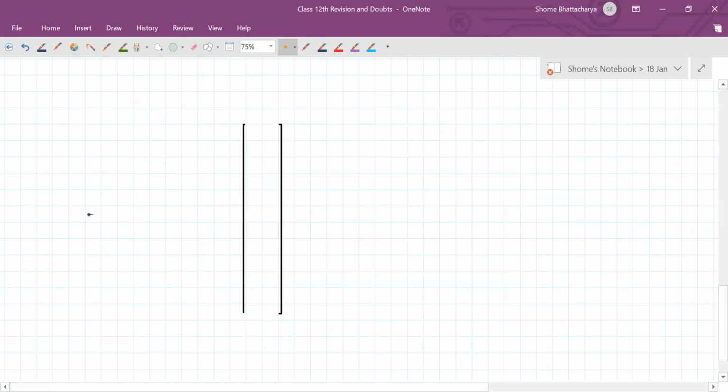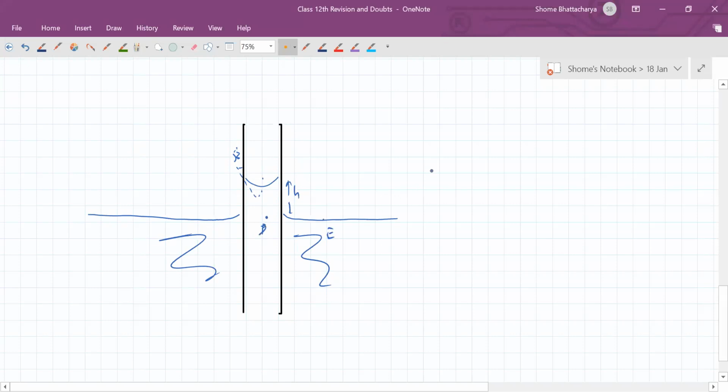As the liquid is coming in, it is at that contact angle initially of 53 degrees. So it has maintained this pressure difference. Now this h is not enough to make this point's pressure equal to this point's pressure. So pressure at the point D is still less than pressure at the point E because this is creating too much pressure difference. So liquid continues to rise all the way till it reaches the top. And even then, with the natural contact angle of 53, there is too much pressure difference across the meniscus for the height of the liquid column to be able to compensate.